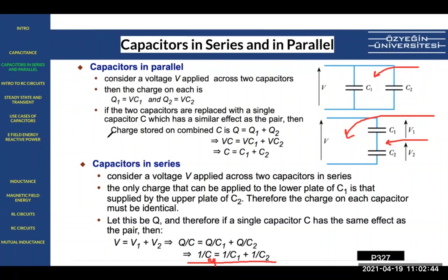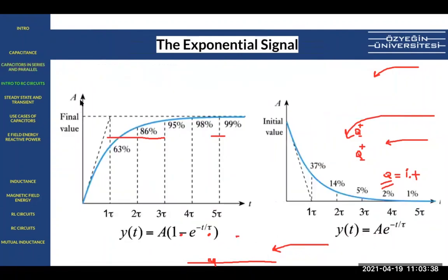And the reason is coming from the concept of charge. For instance, in the case of the two caps, well, let's check. So here, the total charge, this one is Q, and what should be the charge in this one? It should be Q, right? Because they have the same current. Q is current times time. So since they're in series, their current is the same, so they should have the same Q. So that's where the proof is coming from. Yeah? So you can check these slides. I won't really have time to explain the proofs, but these are concepts you need to know.